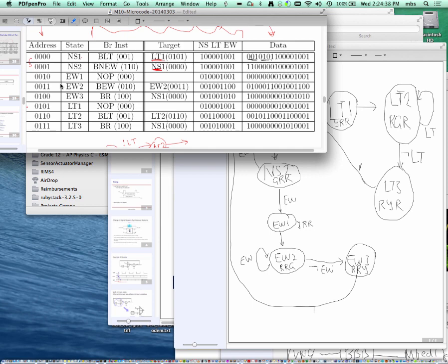Now, if you are using a processor which is given to you, then you have to abide by whatever you have. If, on the other hand, you're designing your own logic entirely, then you can define your instructions. So if you decide that you need five outgoing edges, then you can define a five-way branch. The problem you face with microcode is that I can only specify a single branch target. I cannot specify five different arbitrary branch targets. So then we start playing games.